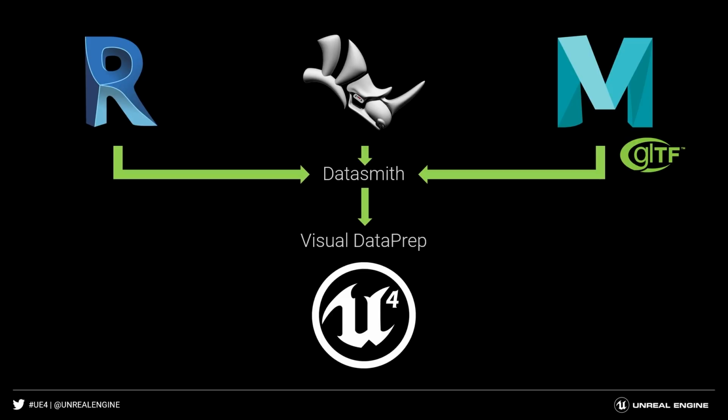And then from there, we're going to import the Datasmith files into Unreal, but rather than use the normal way of importing those files by simply importing from the Datasmith button, we're going to use the Visual Data Prep tool.